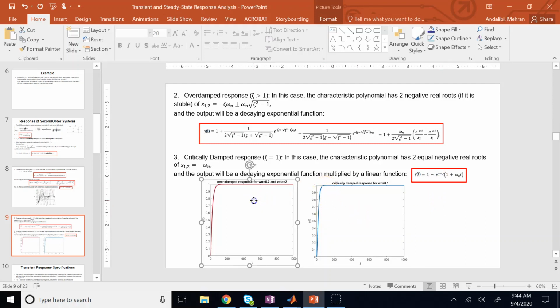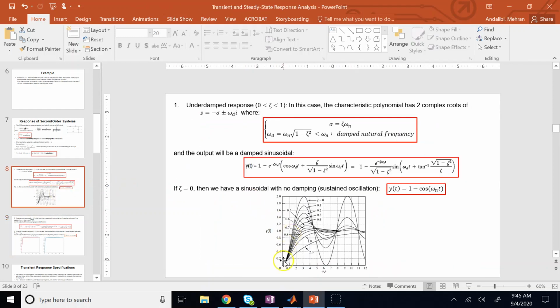And I can show you again later that actually this guy here converges to the final value faster than overdamped. So if you want the fastest response, which means you reach the final value in the shortest time possible, the best way to do it is using critically damped actually instead of overdamped. This converges way faster than that one. Not way, but quite. And both of them are typically quite getting faster than underdamped, depending on how you tune the system.